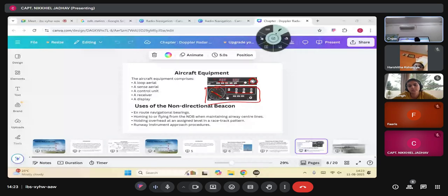One big one on the outer circle, and a small one on the inner circle. The big one on the outer circle will switch the frequencies by bigger numbers. The small one in the middle changes by 0.5. Now you want to set 323.5. You rotate the bigger one to 321, 322, 323. Then you switch to the smaller one, and it will give you the decimal points if needed. Kind of like that.